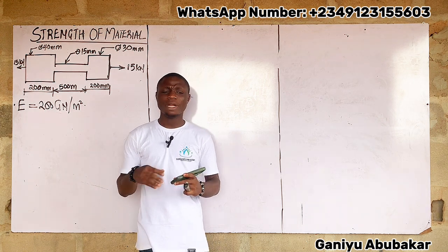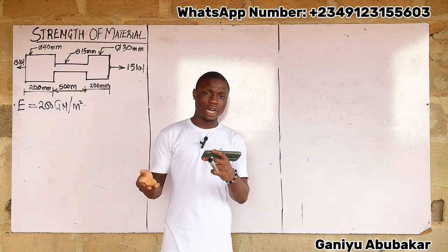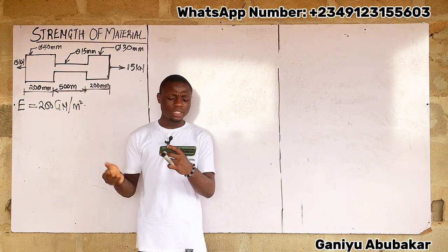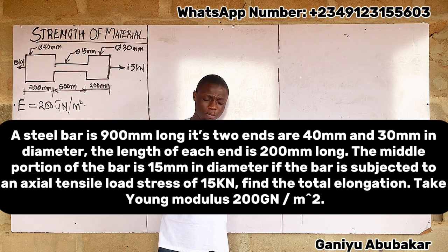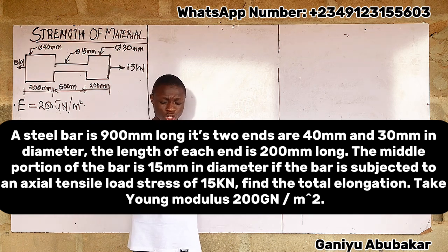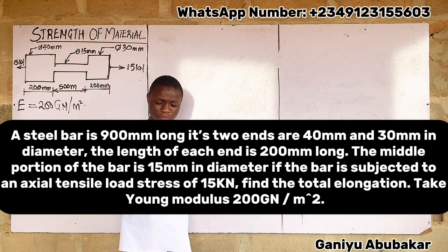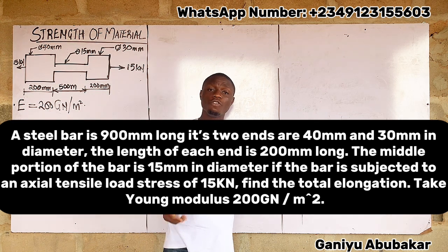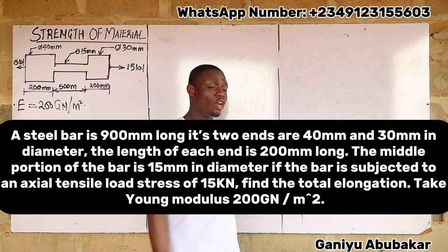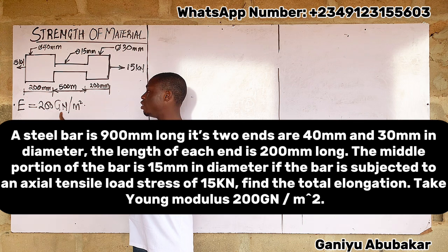All right, let's look at the particular problems for the last 2 years, mechanical engineering. Let's solve this together and let's see how it works. One says a steel bar is 900 millimeter long. Its two ends are 40 millimeter and 30 millimeter in diameter. The length of each end is 200 millimeter long. The middle portion of the bar is 50 millimeter in diameter. If the bar is subjected to an axial tensile load stress of 50 kilonewton, find the total elongation. Take Young's modulus to be 200 giganewton per meter squared.